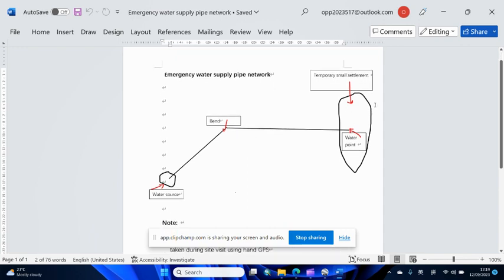Assume that we plan to use Google Earth. Therefore, when you collect data using GPS, set the GPS data format to WGS84. Then you can use it directly on the Google Earth platform.